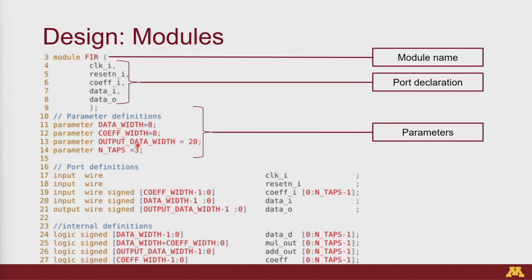But whenever you're writing in Verilog, the first thing you have to do is take a step back and ask, how would this be represented physically? If I had to convert this code to a physical block of hardware, would that be realizable? That's the question you need to keep answering as you do your design.